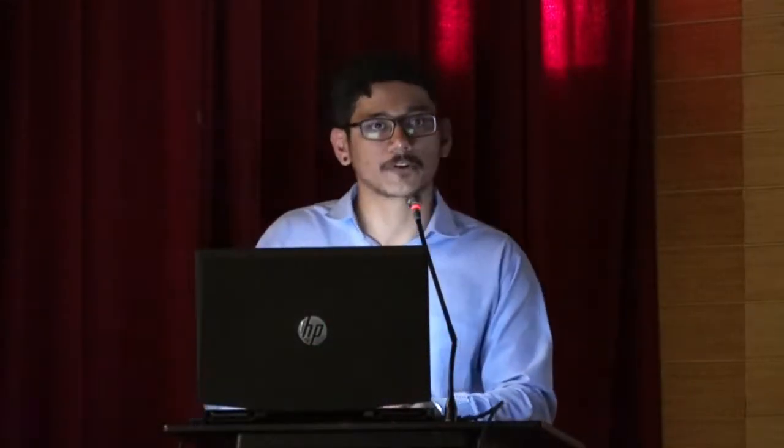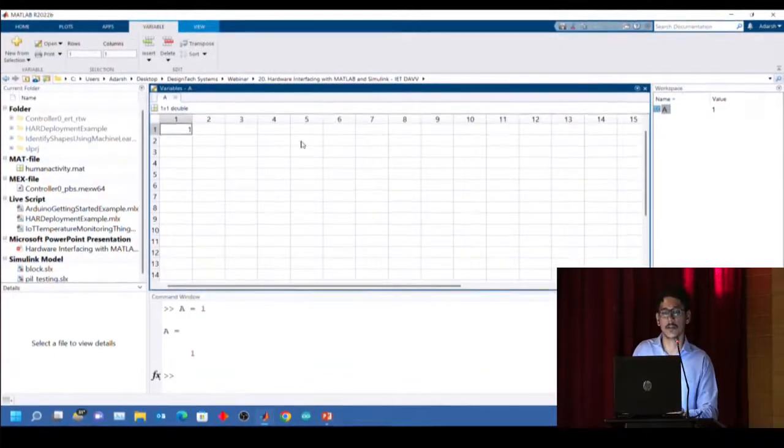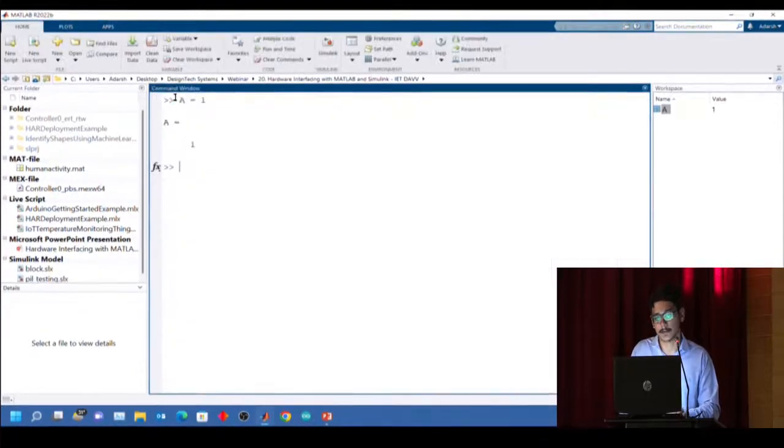We call it workspace browser. Whatever variable we create here, if I write any command like this, all the variables will be visible here in the workspace. This can be helpful to analyze, if sometimes you get errors in your code, you can check why your error is coming and whether the variables have some corrupted value, because of which we are getting the error.